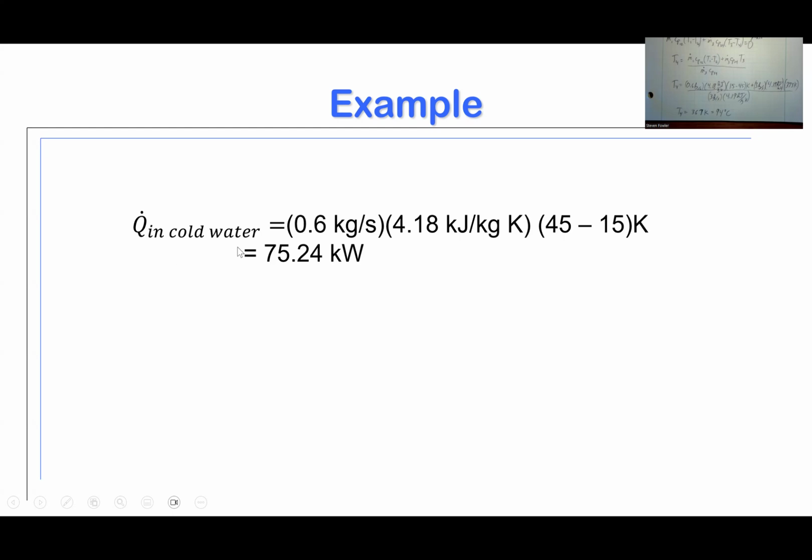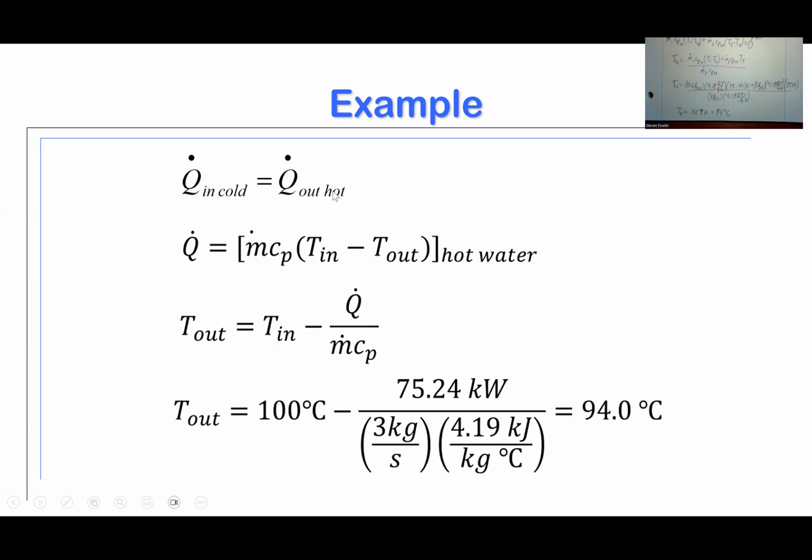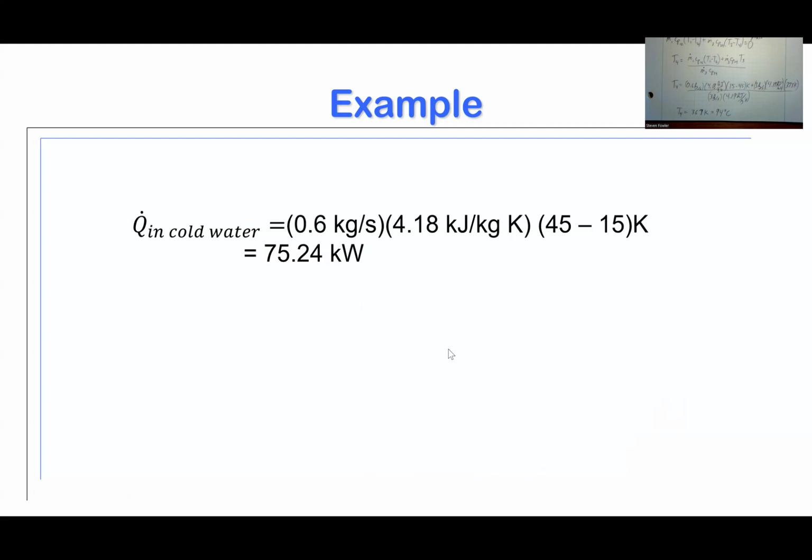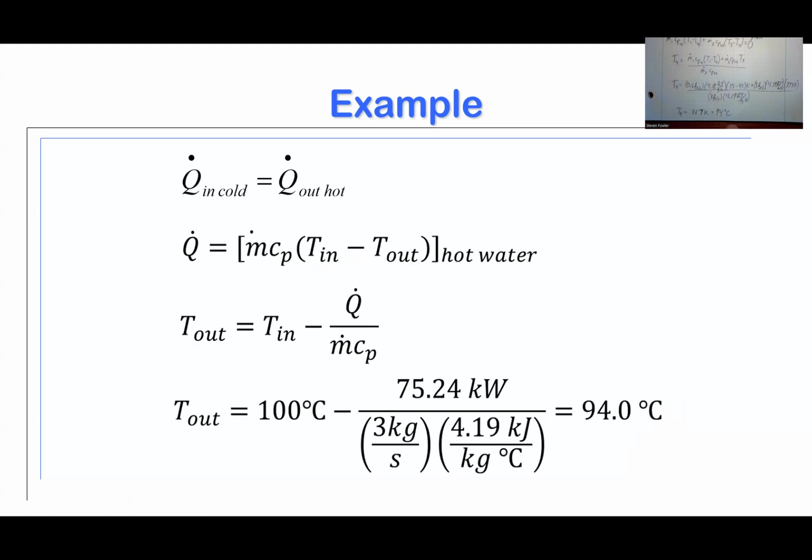And then that is the amount of heat that is being lost by the hot stream. So if I set up a first law for the hot stream, then the heat lost plus the energy of the mass in minus the energy of the mass out, that sum's going to be 0, and then just do your algebra. Then I can find the temperature out for the hot water. You can see here, we can set up and get the same solution as what we just found, treating it as one single system. Either way is perfectly fine. If the problem asks for this heat transfer, this is the only way you're going to be able to do that. I think in the original problem in the book, in the current version, it does ask for this heat transfer. Then you will have to set it up as 2 different streams and find the heat transfer between them. Just finding the one unknown temperature, you can see mathematically you've got the same thing here.